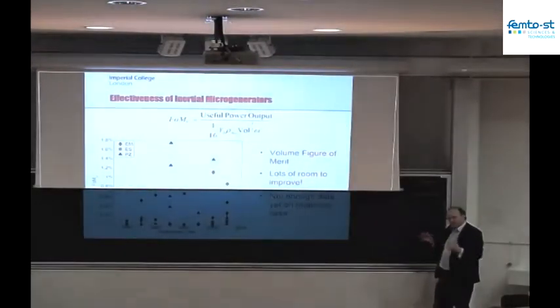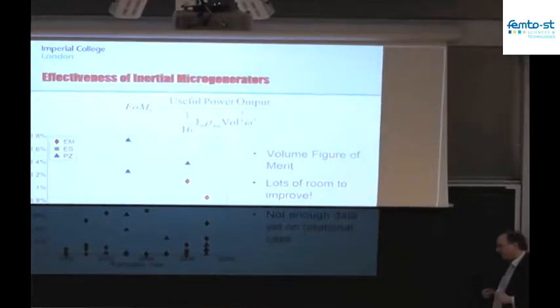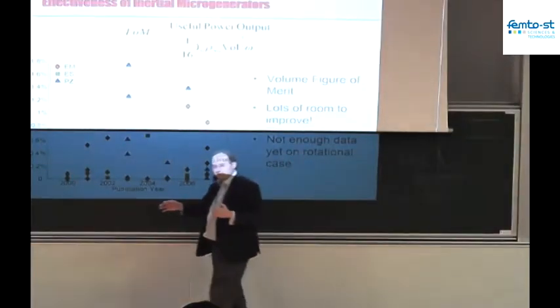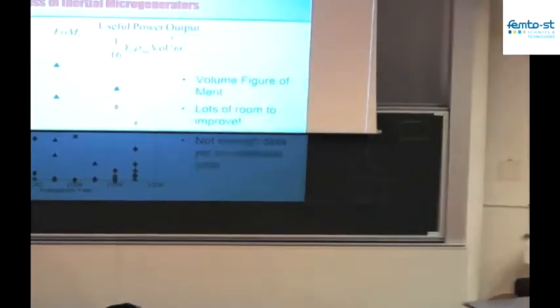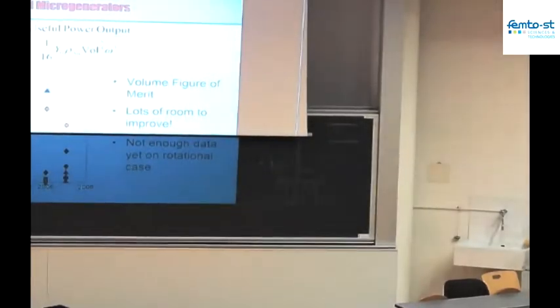So if you think about this purely in electrical terms, what it means is if I've got a voltage source at a particular frequency, I could only get real power from that voltage source if I pull a current at the same frequency. And you know that if you pull a current at the same frequency, if it's 90 degrees out of phase, that also means no power. That's like just putting a capacitor onto an AC waveform. There's no real power transferred. But if you have a voltage at one frequency and you pull a current at a different frequency, then there's no real power transferred. It's just energy sloshing back and forth. I can play exactly the same trick on the energy harvester.